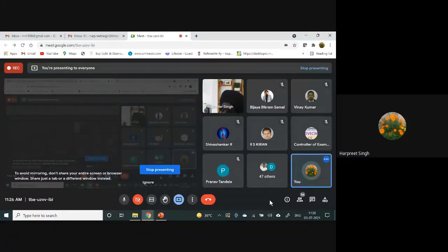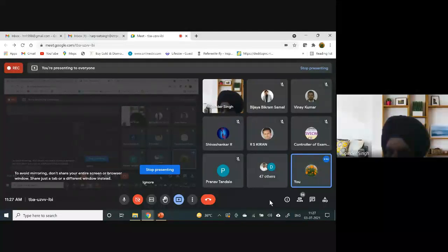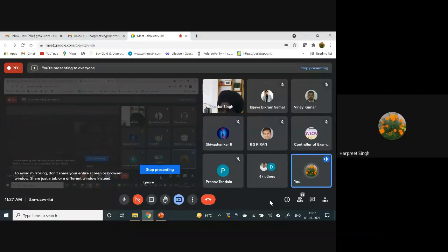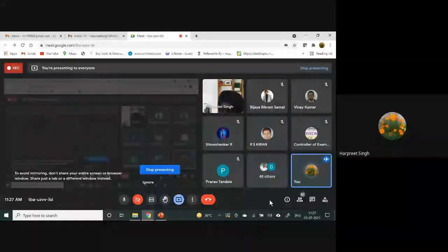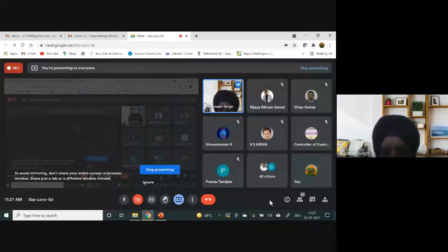Specimen preparation is very, very critical in all these cases. Sometimes we end up damaging the grain structure, and sometimes a few seconds more of exposure to etchant spoils everything. So why don't you first take some idea from SEM images and then slowly move into this one. We will discuss the specific problems with you maybe after the discussion.